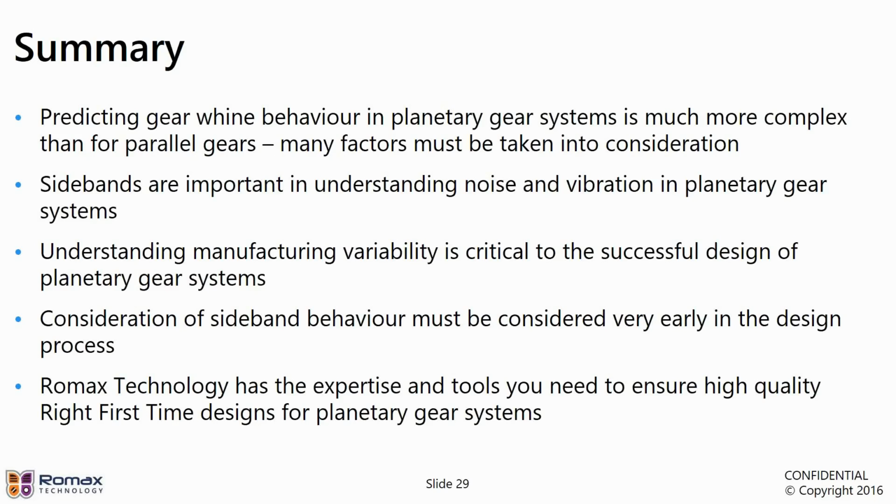Just to re-emphasize this point, because it is so important, we must understand the manufacturing variability and how that affects both the noise at the gear mesh frequency and at the sidebands, and is critical to our successful design. And we've also seen the importance, because of the fundamental nature of the parameters that affect this, we need to consider the sideband behavior very, very early on in the design and development process. And hopefully you'll agree with me that we've seen that our tools here at Romax and our expertise, we have all those things that you need to ensure high quality, right first time designs for planetary gear systems.